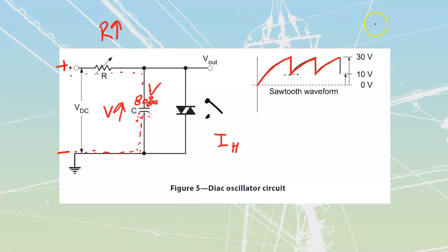We've got to have a gate. You guys remember these at this point. We're going to have our triac. I'll just draw a quick triac over here, and that triac is going to have a gate, and we have to have a little bit of a gate pulse. Well, if we build this circuit right, we can select correct values for this, correct values for my triac, so that anytime it hits this peak, it's going to be enough power, my I gate and my E gate, to gate this larger load carrying component over here, my triac itself. We can use them for SCRs as well.